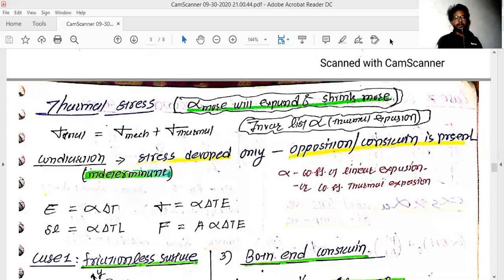On the basis of this coefficient value, the effect of temperature on a particular material behaves in a different manner compared to other materials, because soft materials will have a higher value, and materials that are very hard will have a lower alpha value. For example, if you take two examples, steel and aluminum, the higher value is held by aluminum compared to steel.